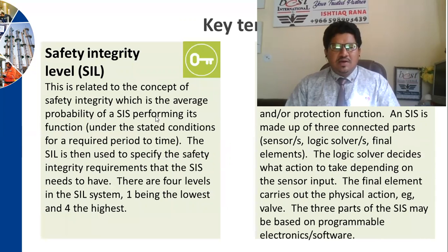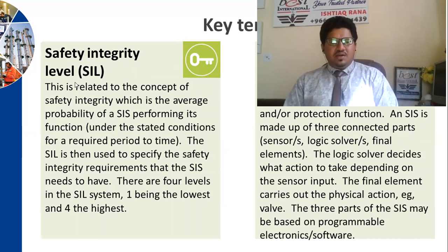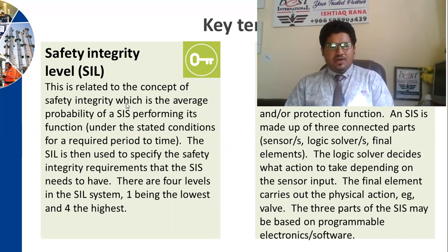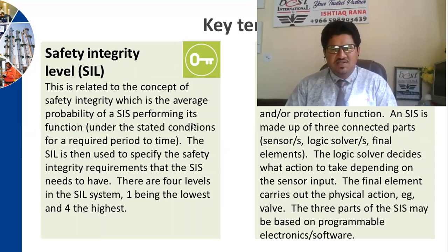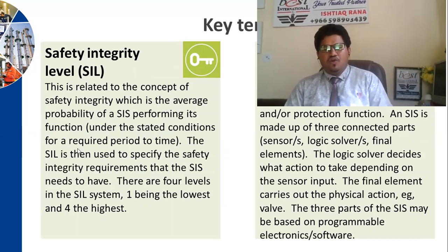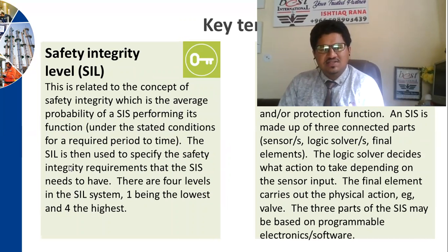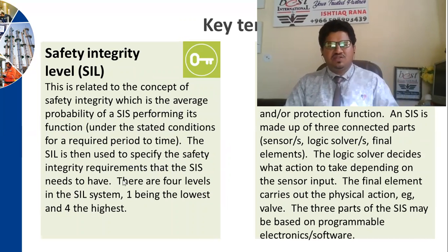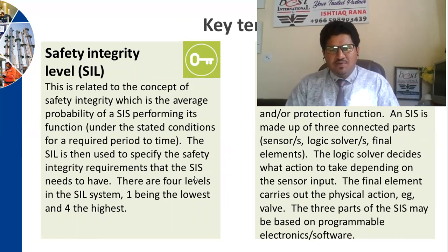Now, what is SIL, safety integrity level? This is related to the concept of safety integrity, which is the average probability of an SES performing its function under the stated conditions for a required period of time. The SIL is then used to specify the safety integrity requirements that the SES needs to have. There are 4 levels in the SIL system, 1 being the lowest and 4 the highest.